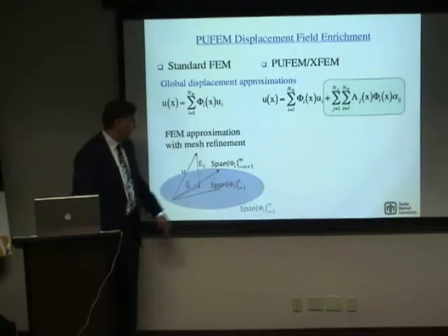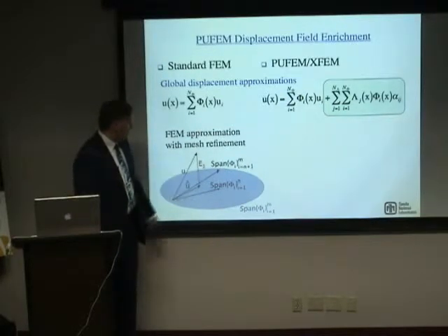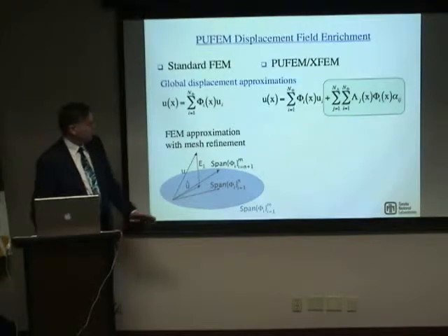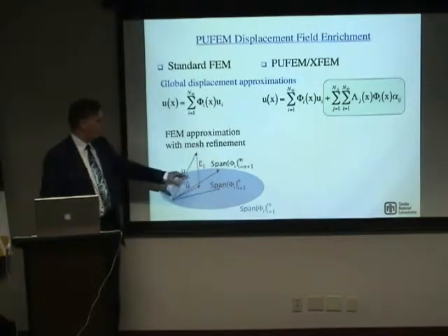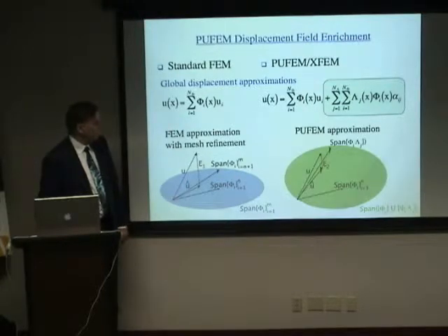So we add an additional set of basis functions through the mesh refinement. And this error E1 now is going to be less than that shown earlier when you had a smaller dimension space. Now you can take these concepts and apply them in the context of the crack problem as well, but then we have to talk about how we're refining this to deal with the crack, so we can think outside of the crack problem at the moment.